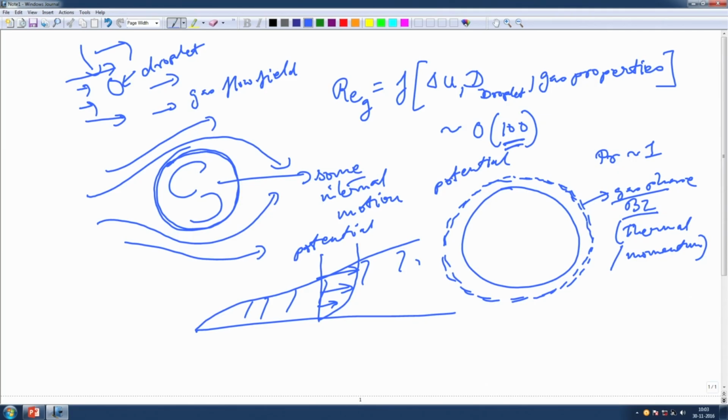And it is quite natural also to see two other things. One is that the liquid vaporization rate increases with Re. Now, to get a clear idea why this happens, let us step back and explain why the vaporization rate should increase with Reynolds number going up.